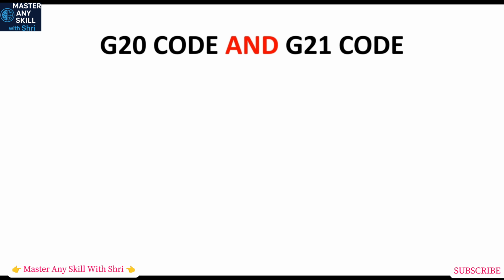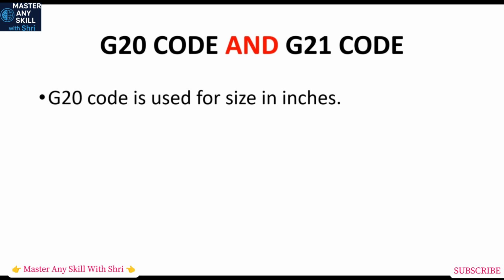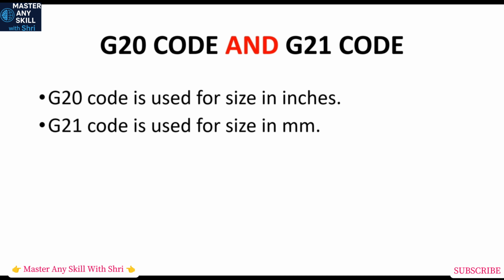Our next code is G20 and G21. G20 code is used for size in inches and G21 code is used for size in mm. That means if you want all your dimensions in inches, then use the G20 code, and if you want all your dimensions in mm, then use the G21 code. Here I have written one conversion formula. 1 inch is equal to 25.4 mm. So you have to know this conversion formula.